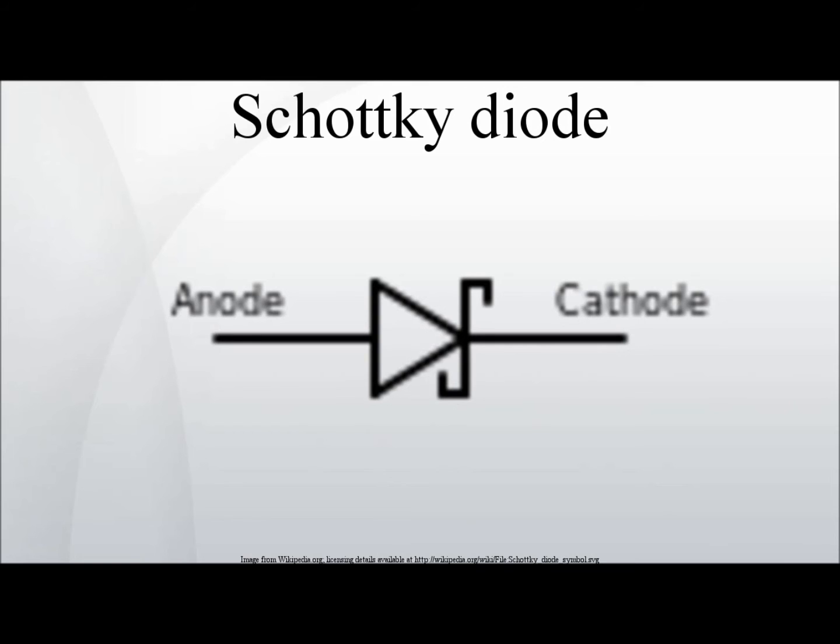The usually employed range is about 0.5-0.7 V, and P-type semiconductors are employed only rarely. Titanium silicide and other refractory silicides, which are able to withstand the temperatures needed for source drain annealing in CMOS processes, usually have too low forward voltage to be useful. Processes using these silicides therefore usually do not offer Schottky diodes.